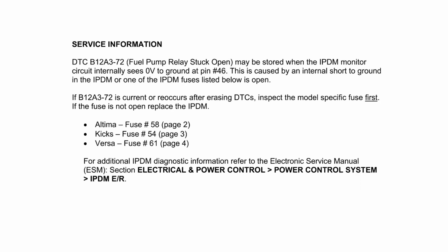So why did I do all this testing? I did all this testing to make absolutely sure you knew how to do the testing, but there's a big reminder right here. Had we started by looking up the trouble code, looking up in All Data any of the technical service bulletins relative to this vehicle, we would have had a very quick answer: if the fuse is good, replace the part. Well, I'm a strong advocate of making sure that you've tested everything. If you use All Data to the best of your ability, it'll avoid you wasting a whole bunch of time.